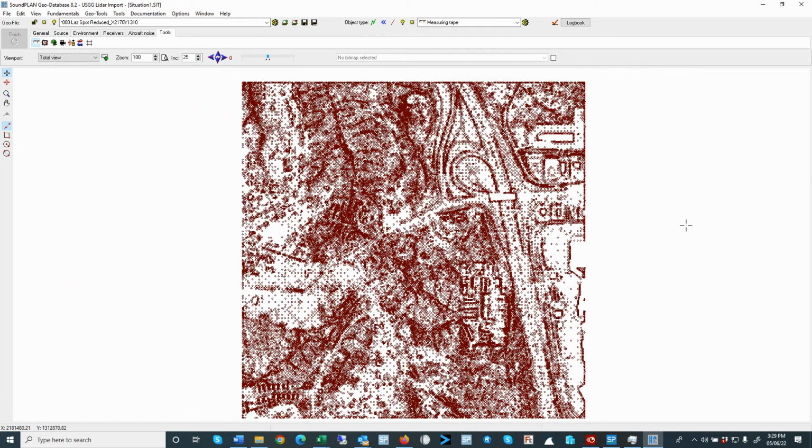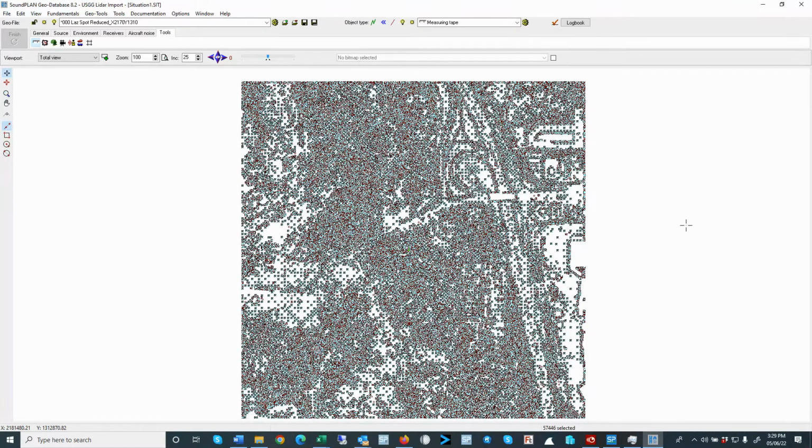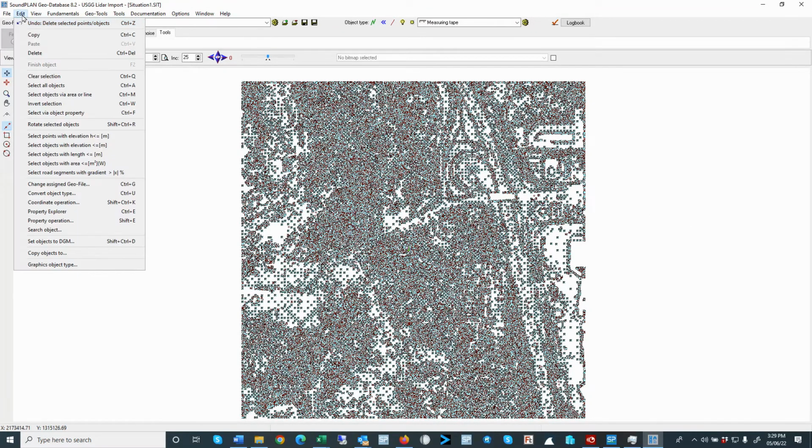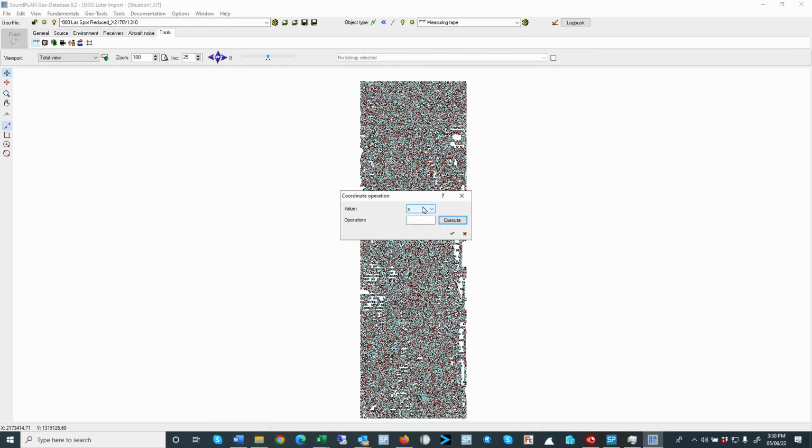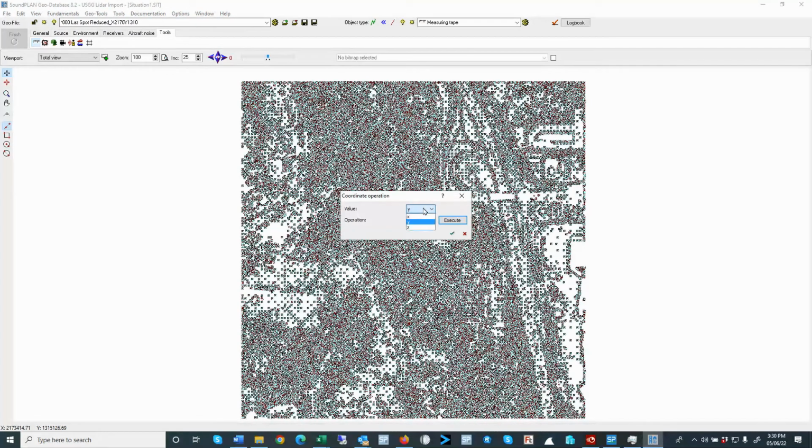Let me go back. We select all, and at this point I'll convert the coordinates in coordinate operation. I multiply the x times 0.3048, I convert the y times 0.3048, and the z times 0.3048. Execute. All right.